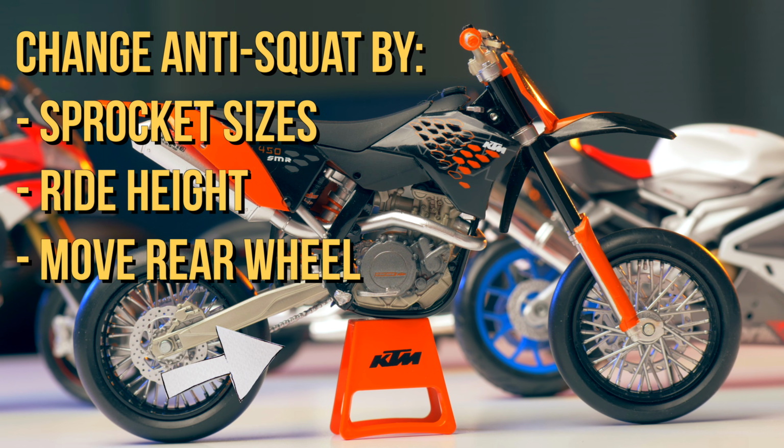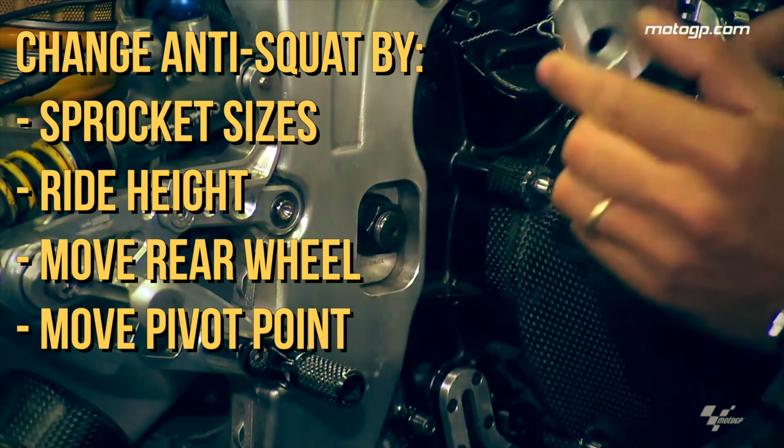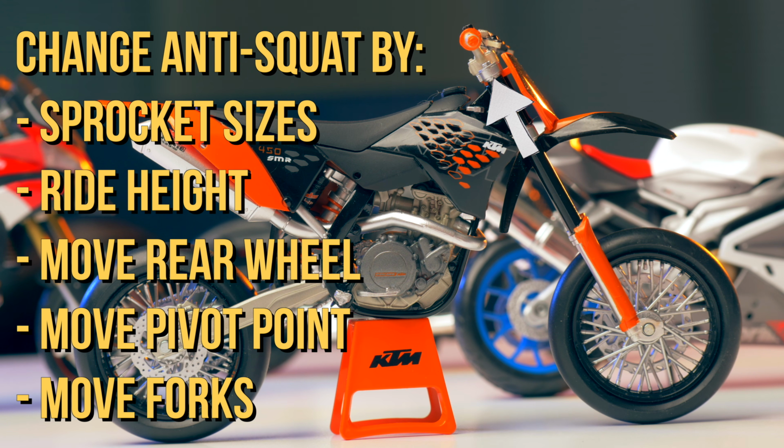Shortening the swing arm length by moving the rear wheel and shortening the chain, which will provide less anti-squat and vice versa. Moving the swing arm pivot point, which is not possible on most consumer available bikes. Moving the front forks and the triple clamps, which changes the swing arm angle as well as the trail. Moving the fork tubes up will decrease anti-squat and vice versa.